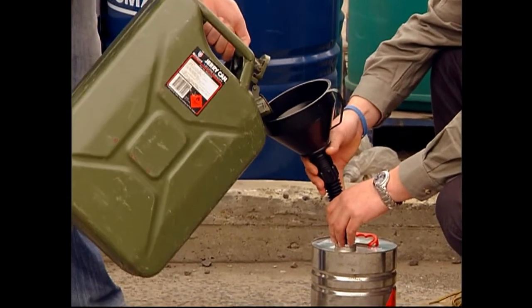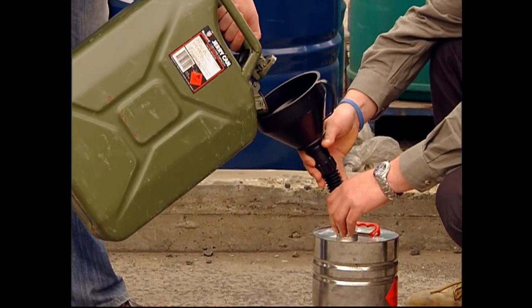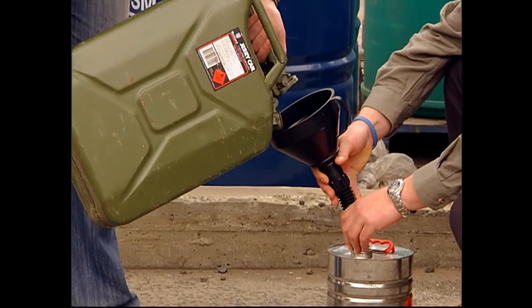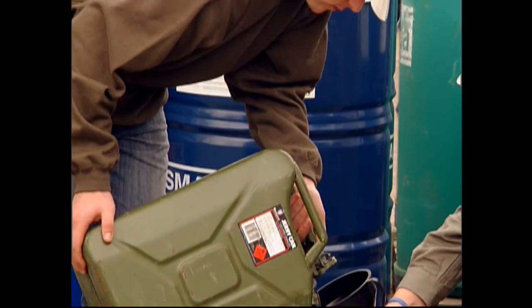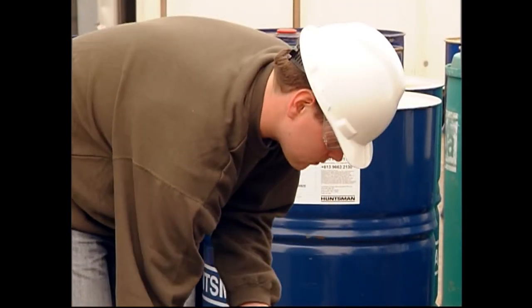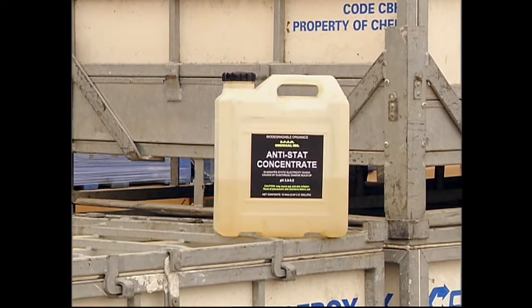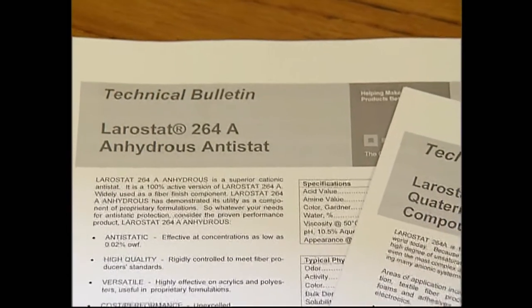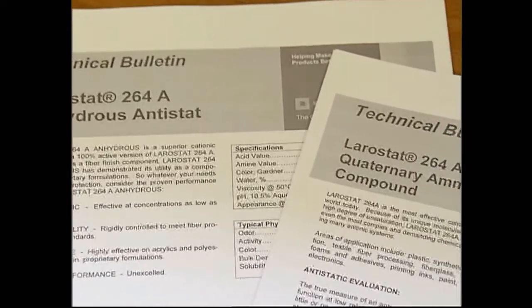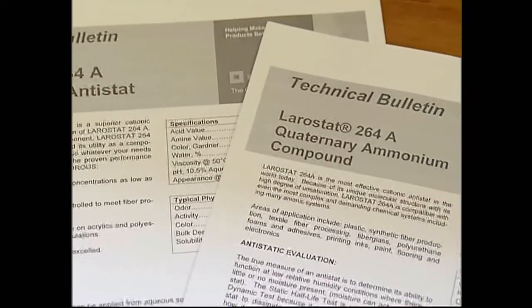When pouring flammable liquids, always pour them slowly. The faster a substance flows, the greater the chance that static charges will build up. Consideration should also be given to the use of anti-static additives. These will act to increase a liquid's conductivity, lower its resistance, and enable charges to pass more easily through the container.